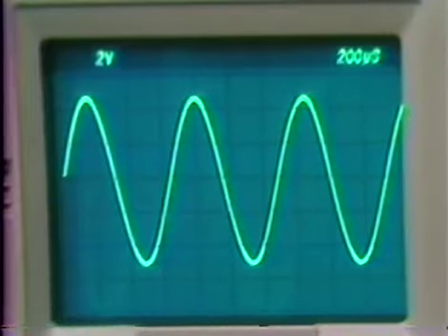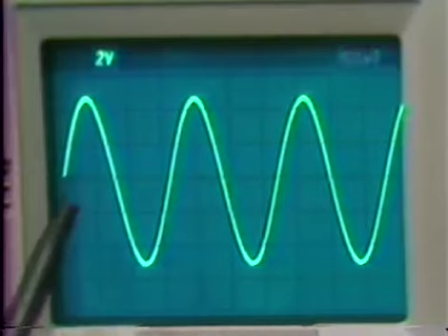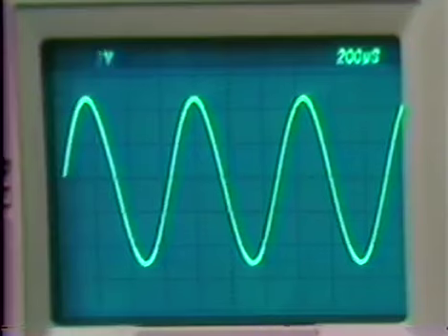To again, within the ability of our measurement, we find that we get an oscillating frequency of about 10 to the 4th divided by 2 pi, a period of something over 600 microseconds, 3 divisions. If you investigate this with a spectrum analyzer, you find that this is a very, very pure sine wave. The sort of distortion we get verifies the basic design principle, the idea of using this as a technique for stabilizing the amplitude of the oscillator.